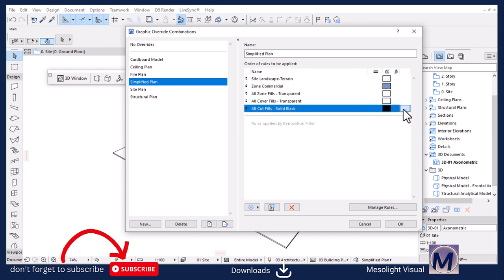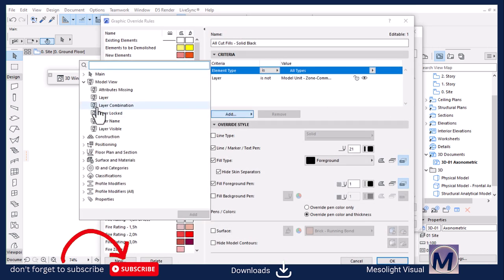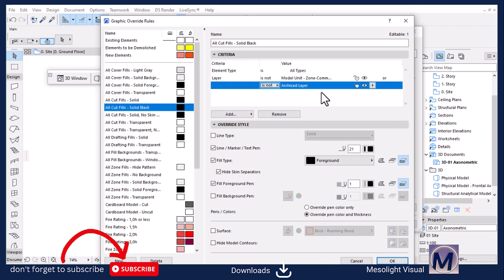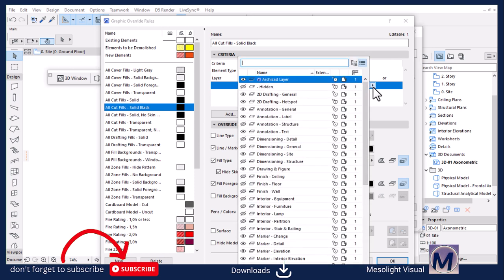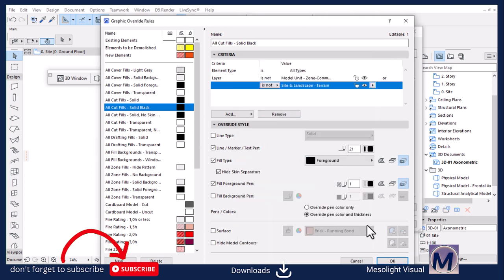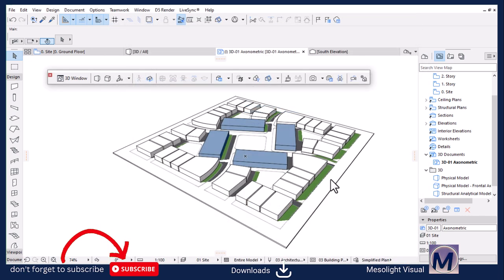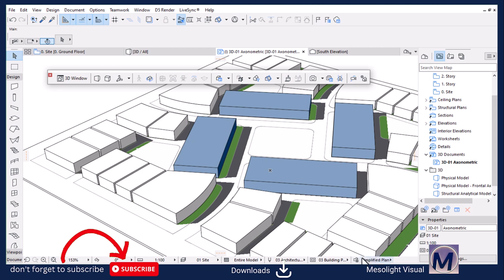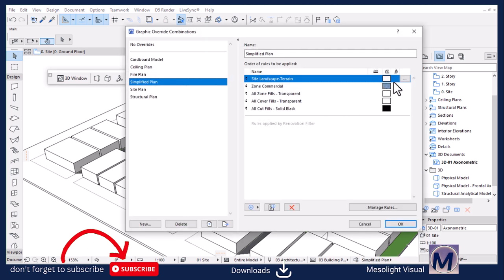So to do that, let's hit edit this rule, and add another layer, saying it's not affected by this ruling, which is for site landscape and terrain. Then hit OK. What happened? It didn't change. Something happened. Let's go back. By looking at the graphic here, you could tell something we did is wrong, because it's supposed to be green.